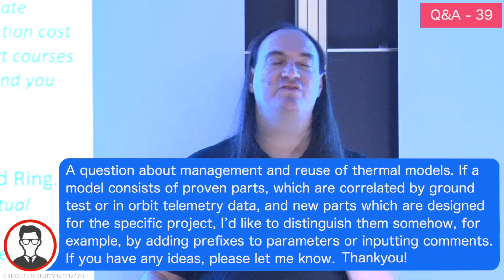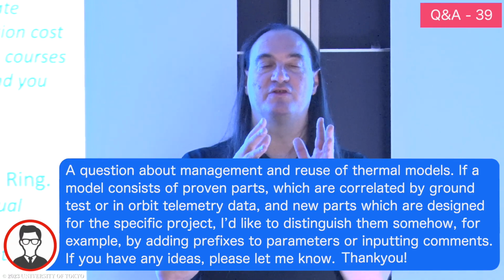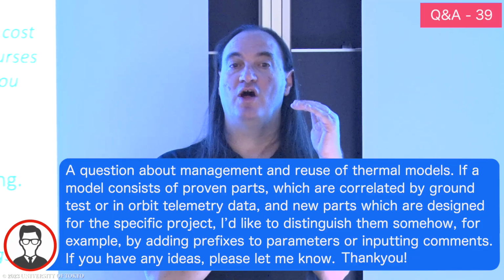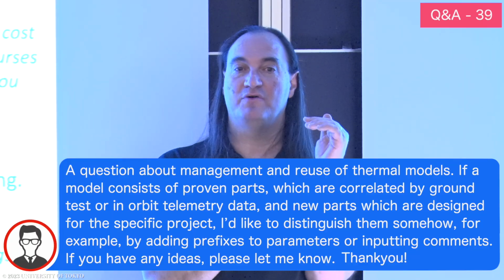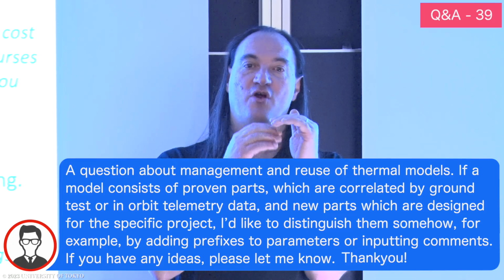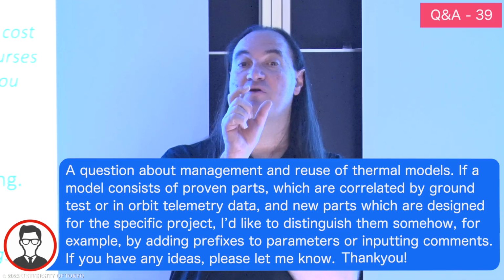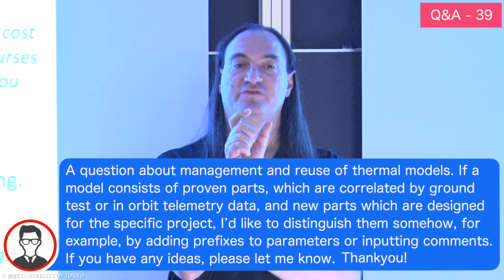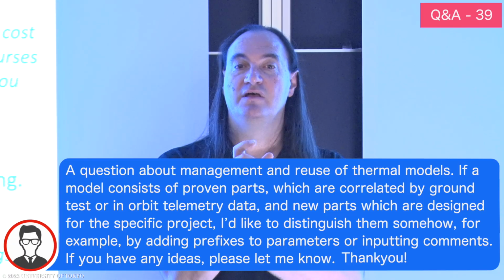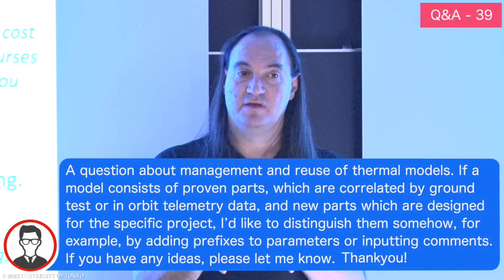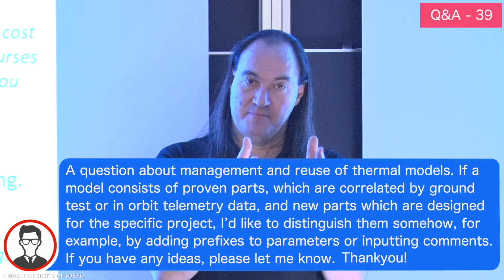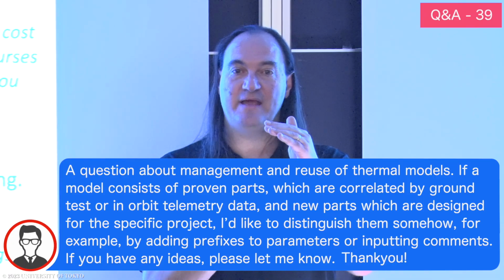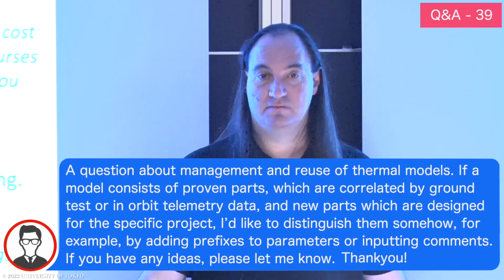One thing to note, if you have a symbol that you wish to change the name for, let's say I have 30 symbols, I could select all of those, and if I do rename symbol, it will bring up an option for all of those to do something. I can either put a prefix in front of them, I can put a suffix at the end, or I can do a search and replace on a particular character. So if you have a group of symbols that you want to rename and put something in front of, you could do that in one swoop. You don't have to rename each one individually. Clear?